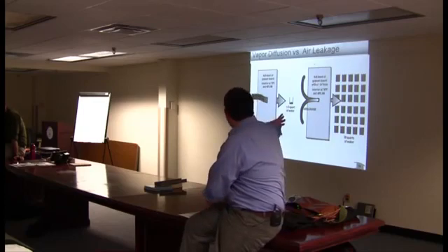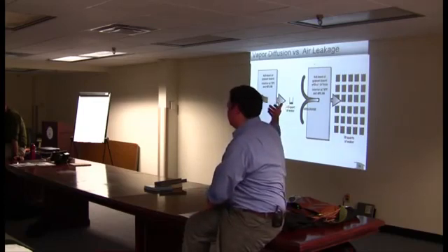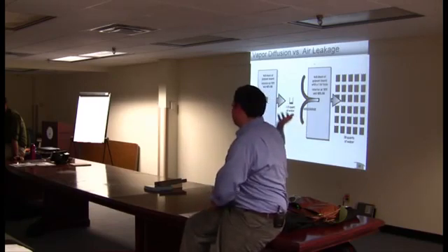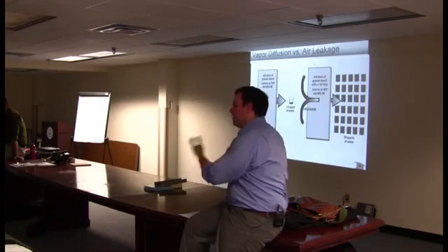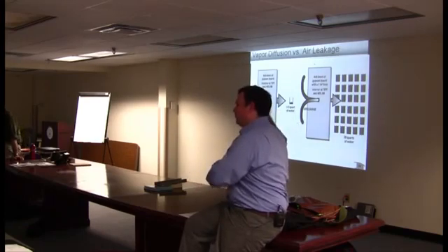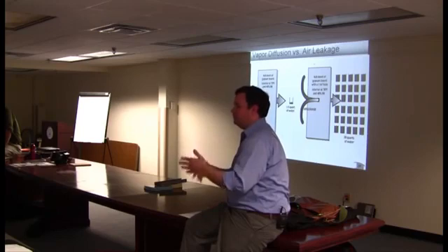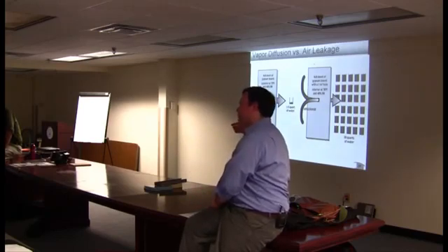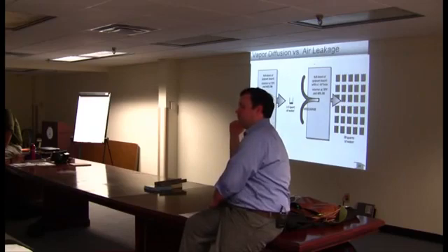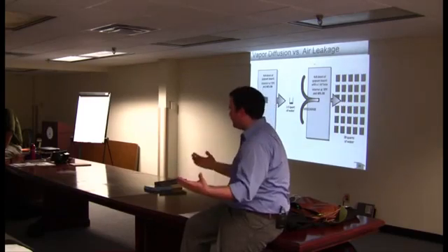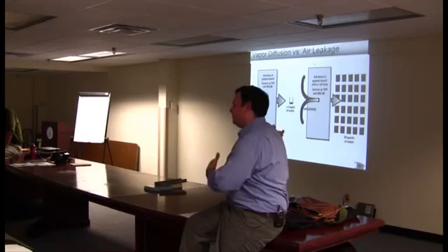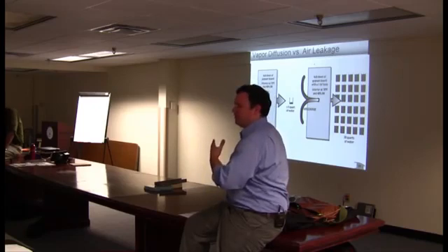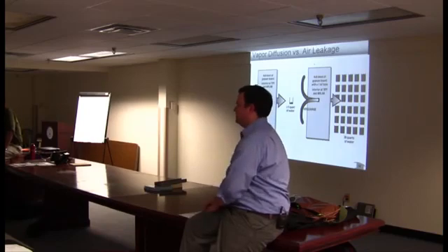So then over on the right, we've basically got the same conditions and the same sheet of board, but we've put a 1-inch square hole in it, and we're looking at 100 times the moisture content. So basically a lot more moisture is able to move through this 1-inch hole than is able to diffuse through the board. So what does this tell us? Which is a bigger issue, diffusion or air leakage? Air leakage. Yeah. 100 times bigger deal. So air leakage is a bigger issue in managing how water vapor is moving through buildings than diffusion is.